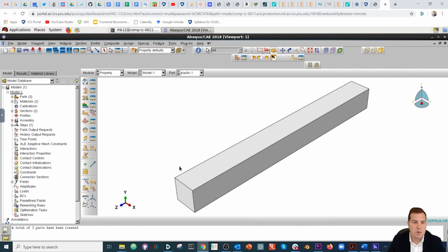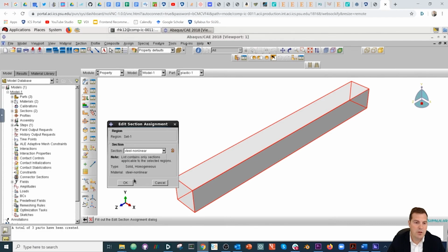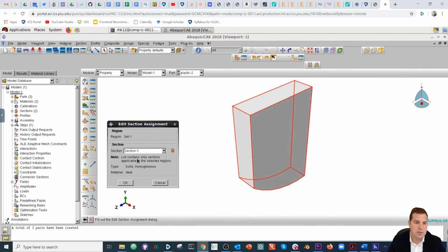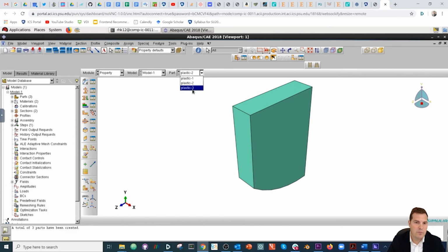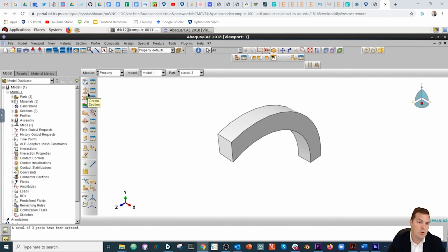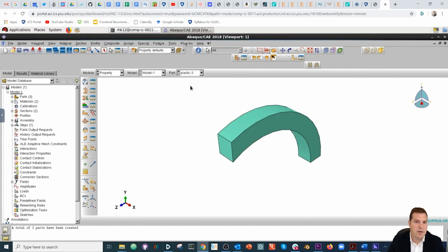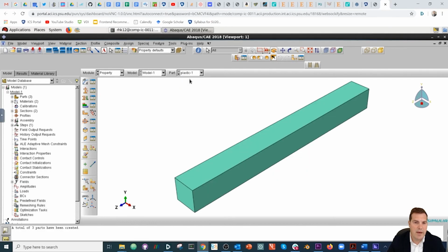So this steel bar is the one we're going to try to bend plastically, and so we'll select this and say give that to the nonlinear, and then the other parts are basically the molds or the anvil, and we're going to select that just to be elastic, so we don't have to worry about the plasticity there, although we could leave it on if we wanted to, but you probably want some hardened steel, much harder than the thing you're trying to bend, right? So you'd have to do that. Okay, so everything is green, which means everything has a material property assigned to it.